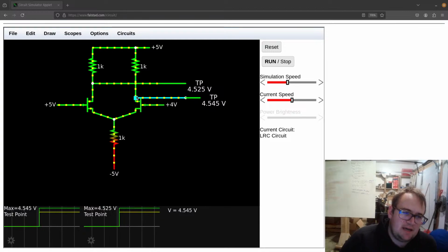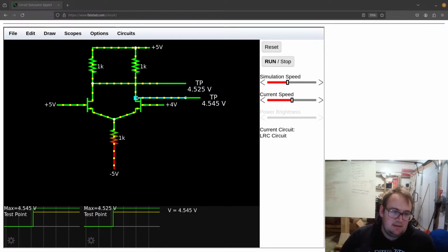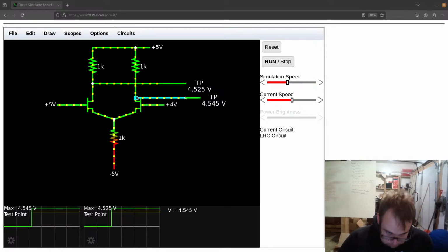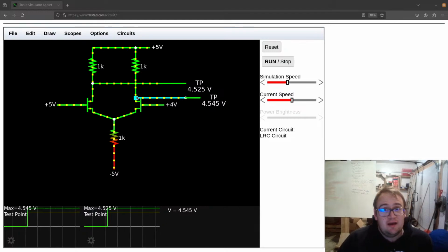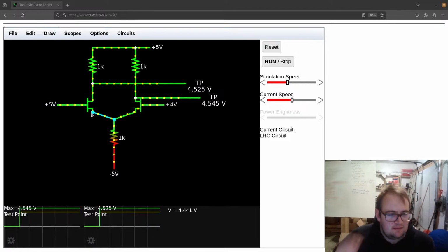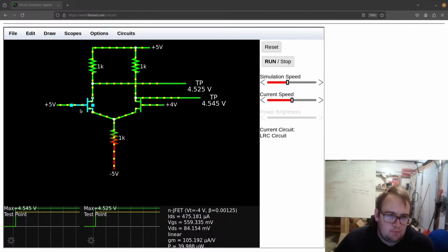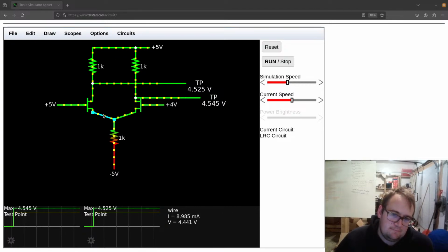The only time we had a JFET was when we built a homemade op amp. There was a JFET there to give a high impedance current source. I just don't, because this gate should be a high impedance input right there. Yeah, it's putting in 10 milliamps.